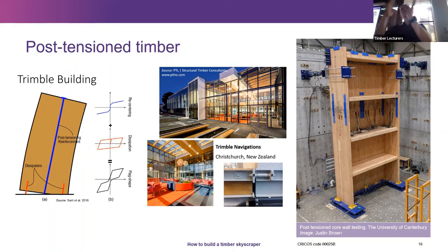And what happens if there's an earthquake? It self-centers. And that's pretty neat because most structures are actually structurally safe after an earthquake, but they have so much residual deformation that it's no longer usable. And you know that serviceability limit state is a failure if it's not met and the structure has failed. So most buildings are demolished after earthquakes because they failed serviceability limit state.